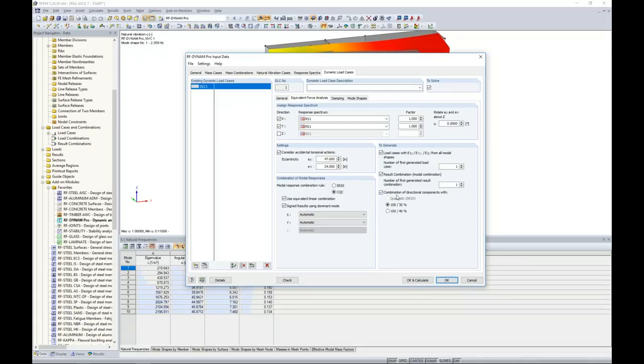Now, furthermore, we have the combination of directional components. And for this, we refer to section 12.5 of the standard, which gives some guidance on the direction of loading. We have forces in the X and we have forces in the Y. So how do we combine these? Well, for seismic design category B, the code tells us that essentially we can consider both of them separately and just look at our results of our structure for each one individually.